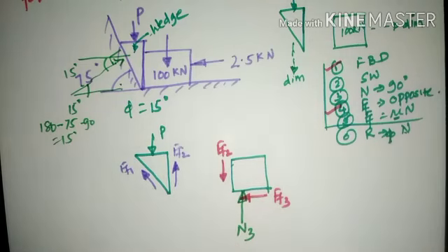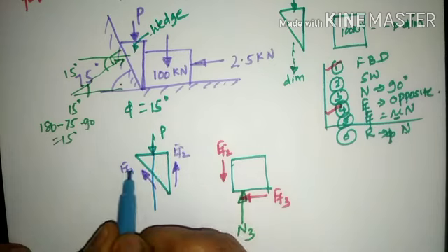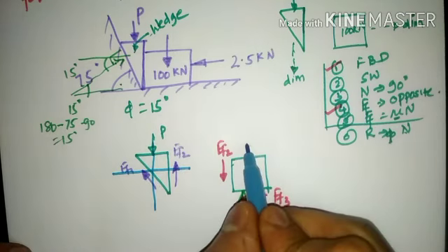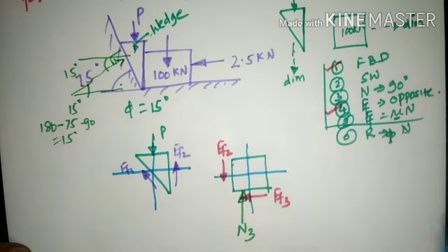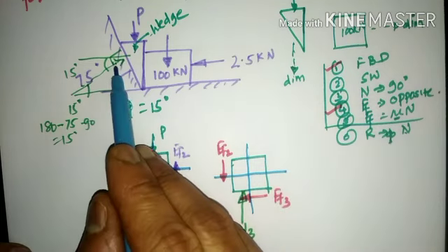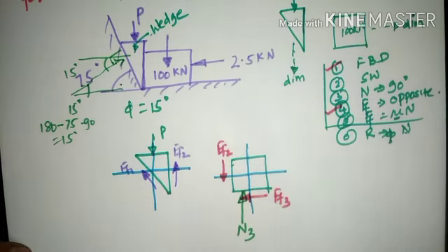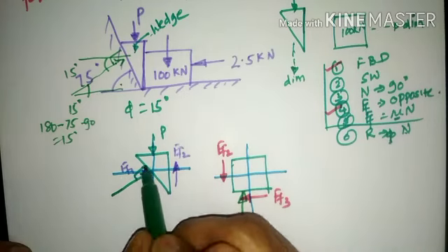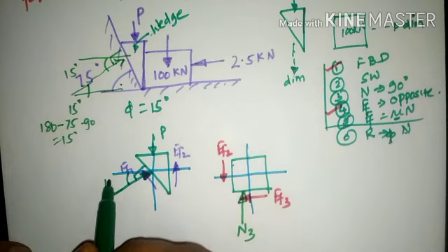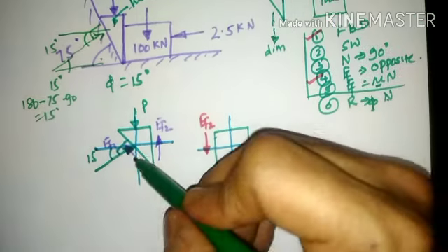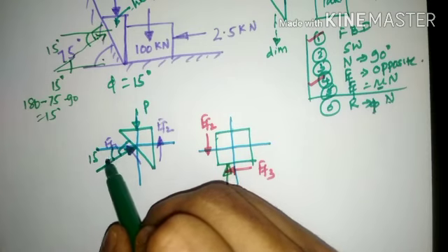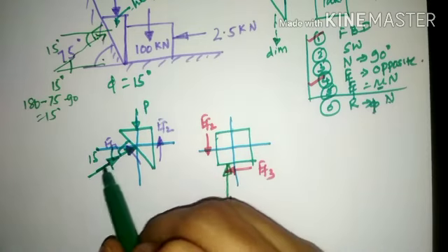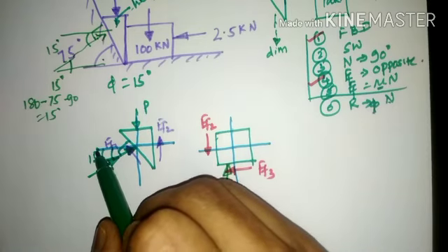If we draw x and y axis for the given diagram, we shall project the y axis and project the x axis. Now coming on to the direction of the normal reaction force component. The normal reaction force component is perpendicular to the plane of contact here. It is 90 degrees. This inclination is 15 degrees here, and the frictional force is upward. The normal reaction is upward, which will make an inclination of 15 degrees to the plane of contact.